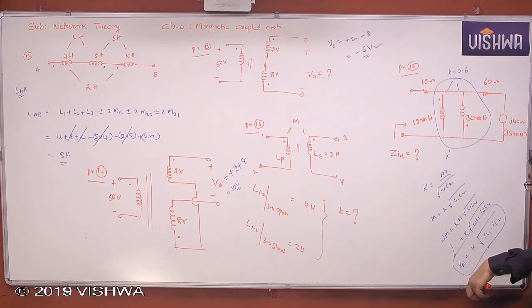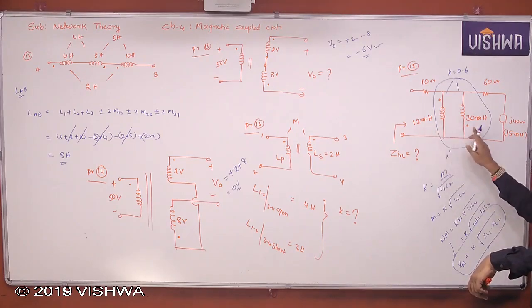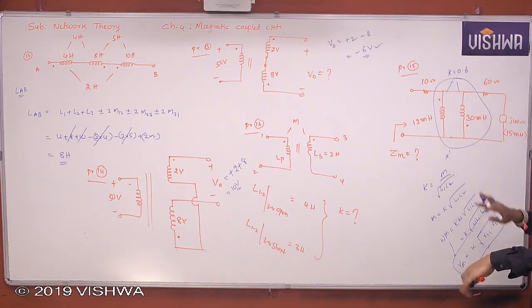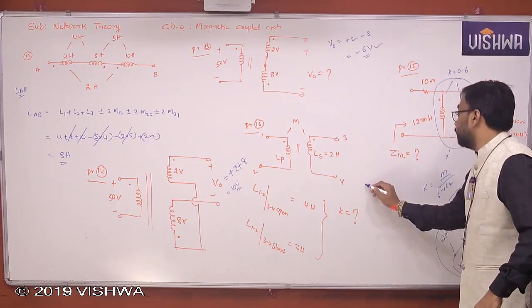So therefore, you have these two. Then based on that, you can automatically find XL1 and XL2. Then if you know that, you can find Xm. Or if inductances are given directly, here reactance is not given, inductance is given, you can find the M value directly. Yes or no, all of you? You need not apply this one. In this case, it may not be useful, but you can also apply like that. Xm can be directly written as K times root of XL1 and XL2, but in this case, it may not be useful. So let us find M.